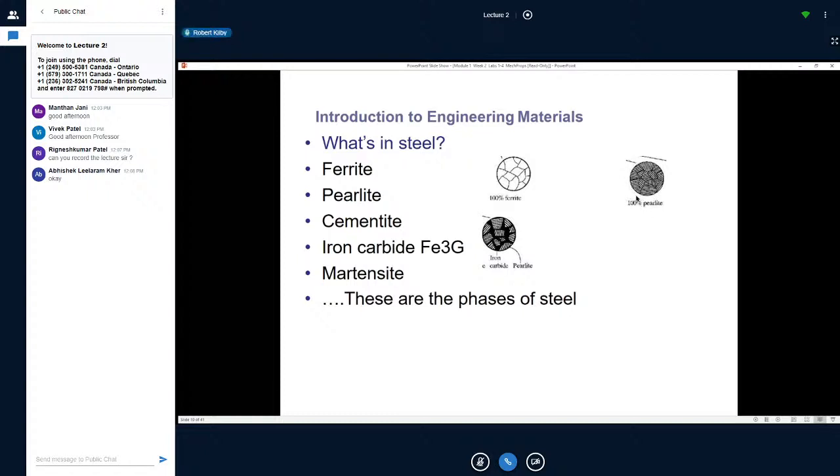As the manufacturer starts adding carbon to a steel as he produces it, it'll start putting in these little straight lines inside of the crystals. When they produce a steel that is at 0.8%, if you think about it, that's not very much carbon, really almost nothing. We saturate the crystals with these, we call them lamellar because they run parallel to one another.